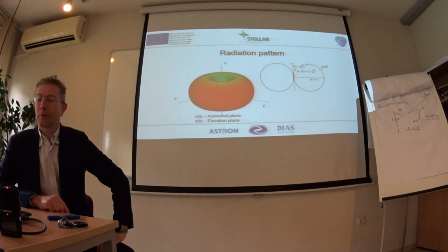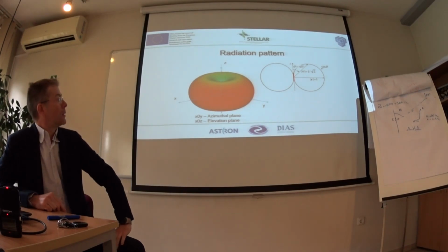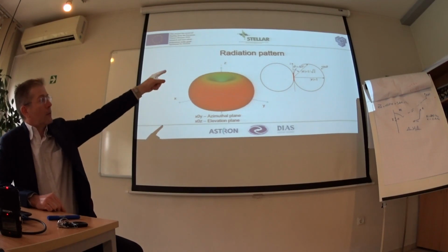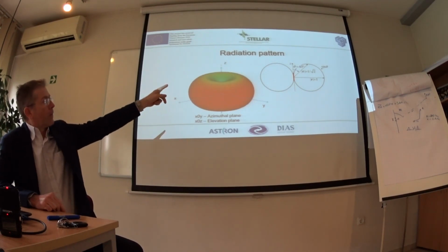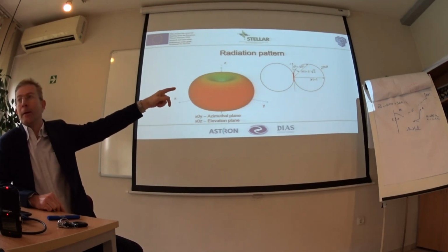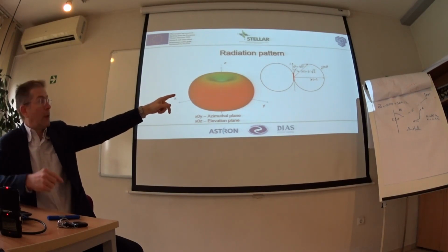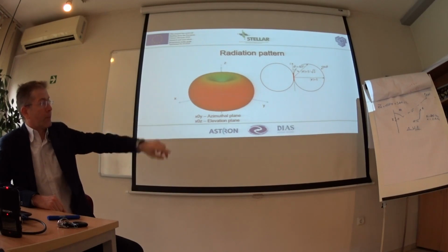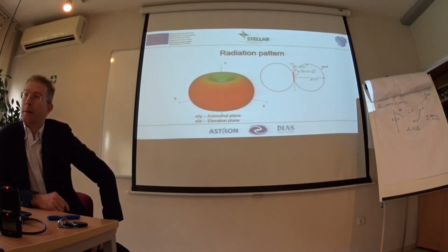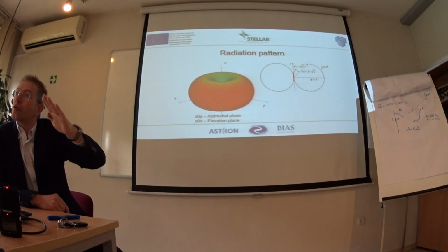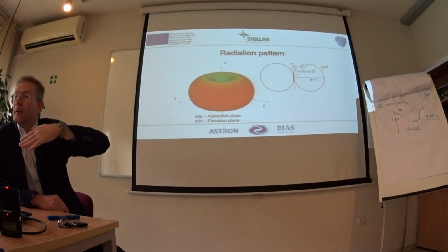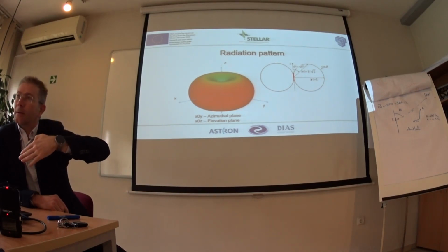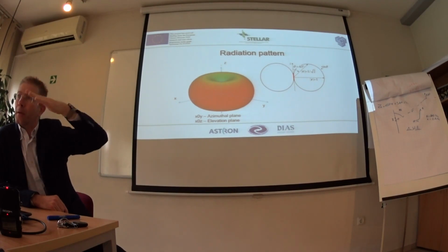Here is what we just have discussed. We have the current in red, and the side. This is called an elementary dipole, a very short dipole. And we have radiation in each direction, but the size of the radiated signal varies with the angular coordinate.